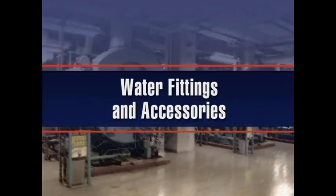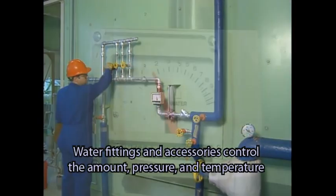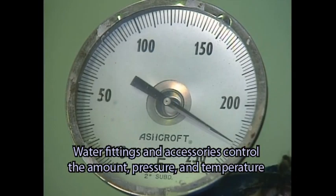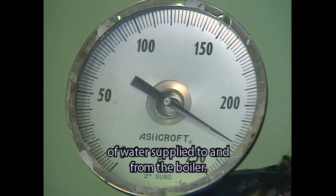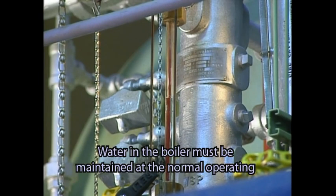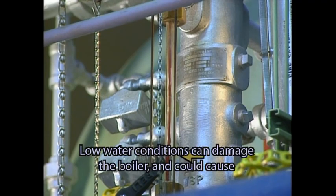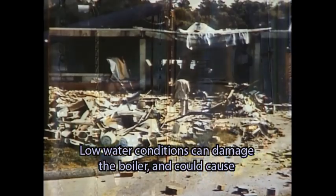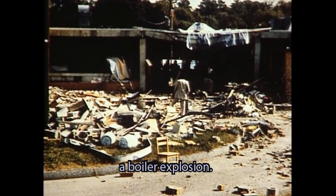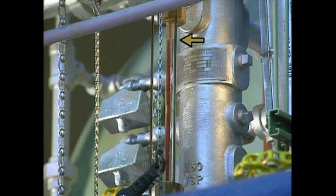Water fittings and accessories. Water fittings and accessories control the amount, pressure, and temperature of water supplied to and from the boiler. Water in the boiler must be maintained at the normal operating water level, or NOWL. Low water conditions can damage the boiler and could cause a boiler explosion. High water conditions can cause carryover.